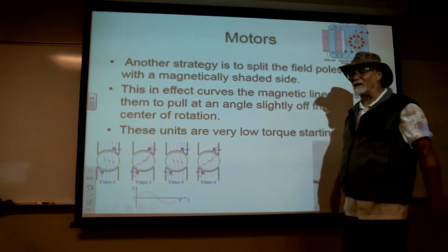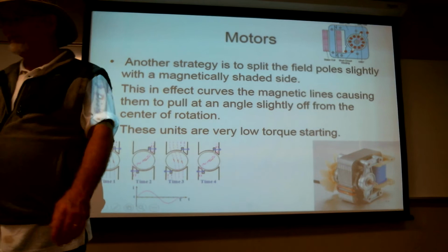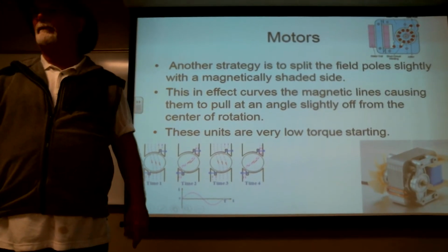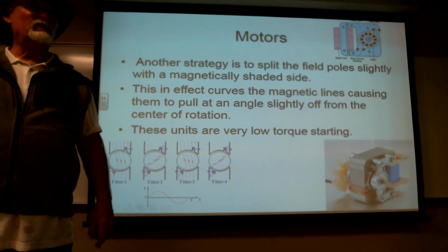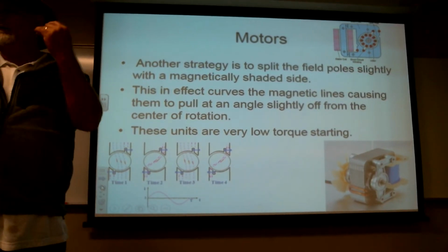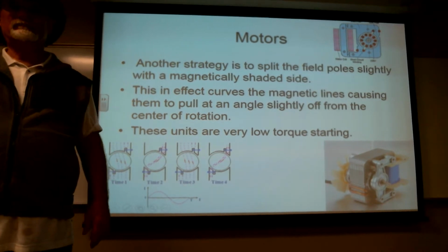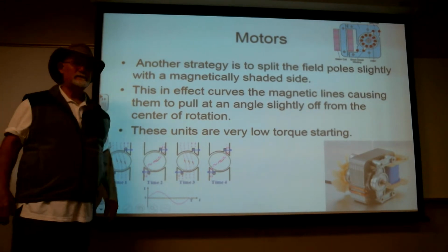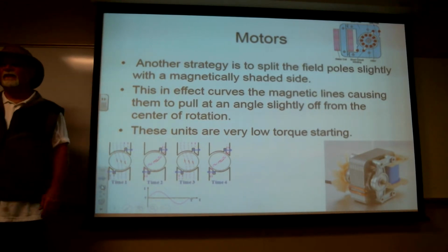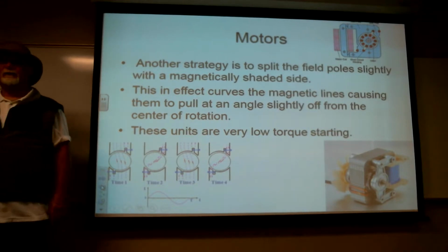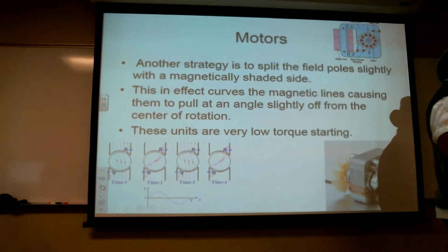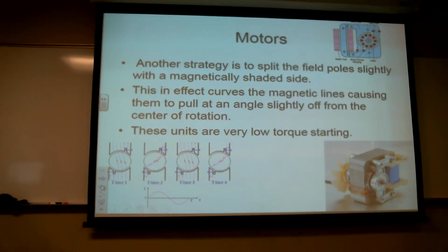Okay, how many moving parts are there? There's one little thing in there spinning around. That's it, a couple of funky little bearings. And as long as this thing doesn't have to start with a lot of torque, it'll go like a banshee. How fast will it go? I don't know. One of the determinant factors is going to be the original frequency of the AC going into it, right? 60 hertz. If I put it up to 6,000 hertz, it'd probably go a lot faster.